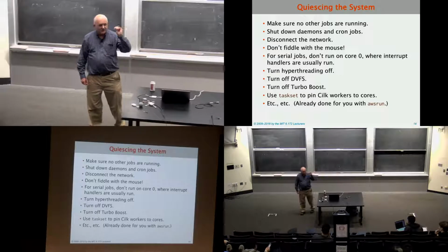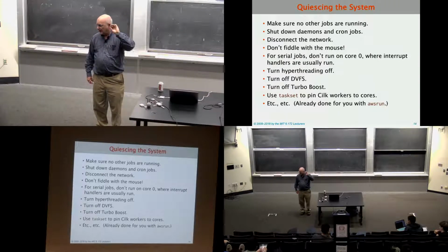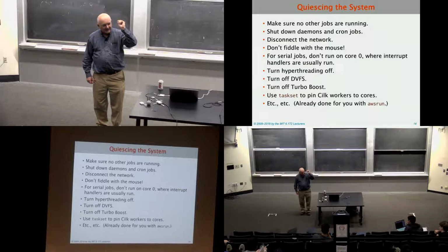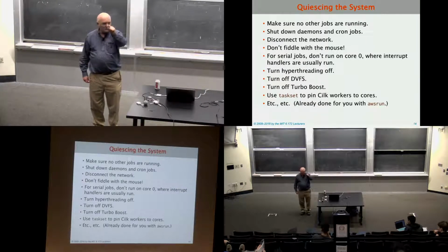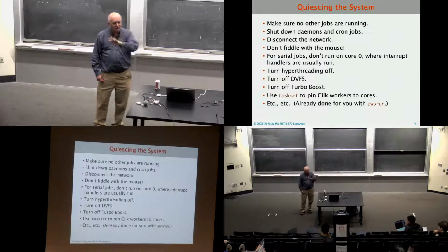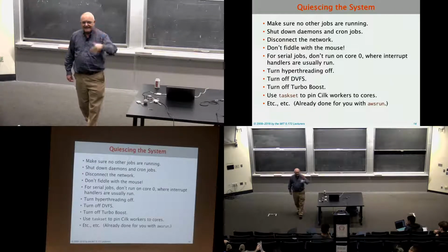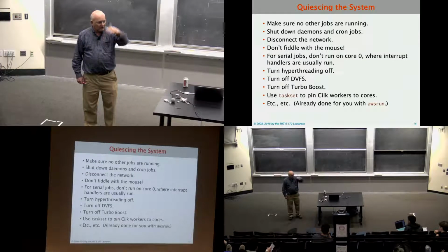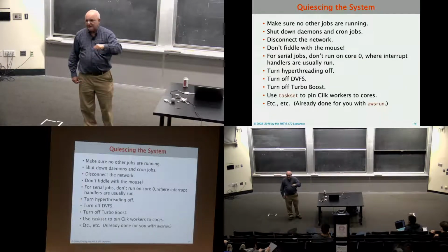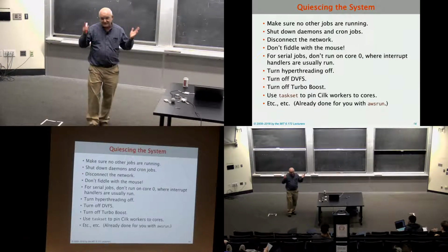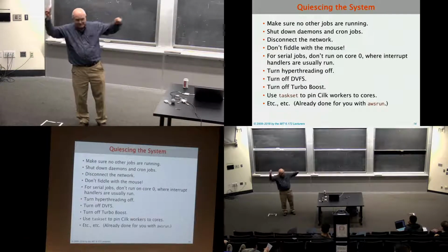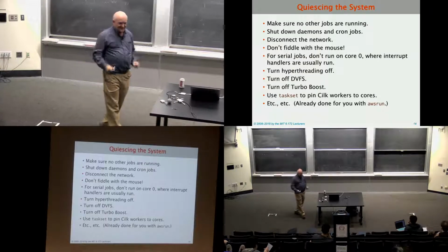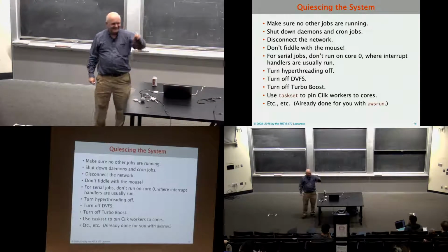So there's a chance that when you're accessing the DRAM, an alpha particle collided with one of the bits and flipped it. And there's hardware in there to do error correction, but it takes an extra cycle to do it. So if it reads the memory location, discovers that there is an error in what it read, then it performs the correction, and then you get it. And that's something that's completely non-deterministic because it's alpha particles coming from outer space, space aliens, messing with your system. Yeah.